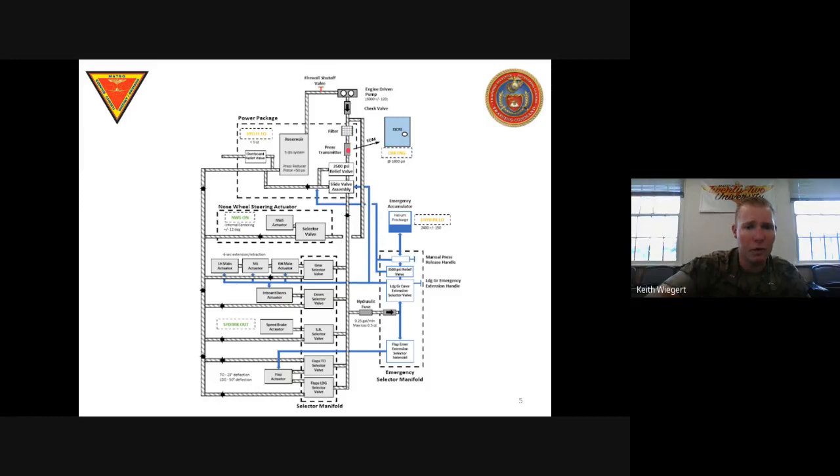Cool. So that comes from the pressure transmitter. Next thing we're going to go through is our 3,500 psi relief valve. That pressure relief valve is going to determine if we do have too much pressure coming out of there. What it's going to do is open up and allow some of that pressure and some of that fluid to vent back to the reservoir, right? And that's going to hit the pressure reduction piston. It's going to drop it from greater than 3,000 back to less than 50 psi in an attempt to reduce that pressure.